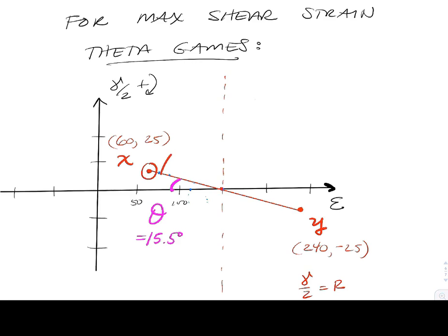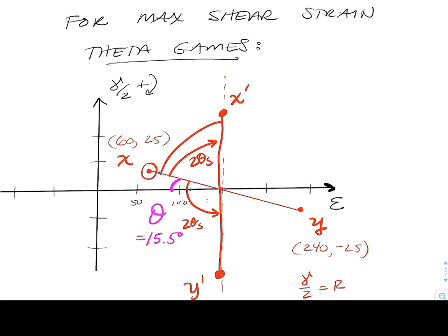So we're going to take that point and now it's going to be sitting up there, and our strain state would be oriented in the vertical direction. To do that, we would strike through 2 theta s. Or we could take the x point and go in the other direction, and now it will be sitting on the bottom. We'll explore both of those here in just a second.